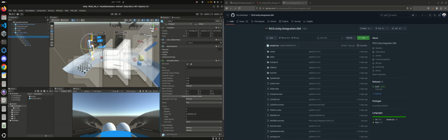Now the next is the link 2. Link 1, link 2 is in this one. Rotate in Z. Okay, that's okay. Link 3 again, link 4, link 5, and link 6. Okay. So as we did in the ROS example, in this case we need to do the same, changing this value, stiffness and damping, 10,000 and 1,000.